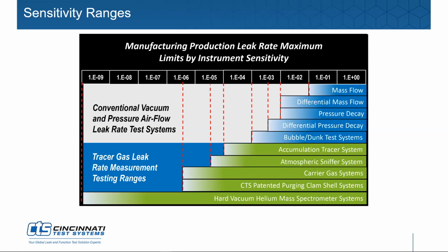So to get lower than 5 parts per million, you actually need to start controlling your background, removing background from your testing environment to see more. Background helium, right? Yes, helium in the background. Exactly. We have 5 parts per million in normal atmospheric pressure. So you either have to change that atmosphere, like a nitrogen purge application, or pull full vacuum, to start evaluating helium compared to that 5 parts per million in your normal atmospheric background.